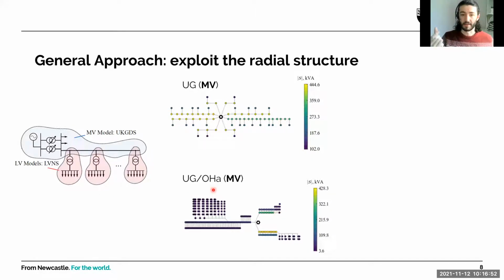One of the limitations of what we developed in that PowerTech paper is that on this network, you've got quite a few relatively big loads, a couple of hundred kVA. We have a whole load of these loads here, which are much smaller, less than 100 kVA. To our knowledge, there aren't good models out there that you can go and stick on the end of these. So in the original models, we cheat slightly in that we take those low voltage networks and pull out individual feeders, which are smaller, and stick them onto these loads that have very low power levels. In practice, these are more likely to be single phase transformers with just 1 or 2 customers, and so the models that we have there aren't so great.